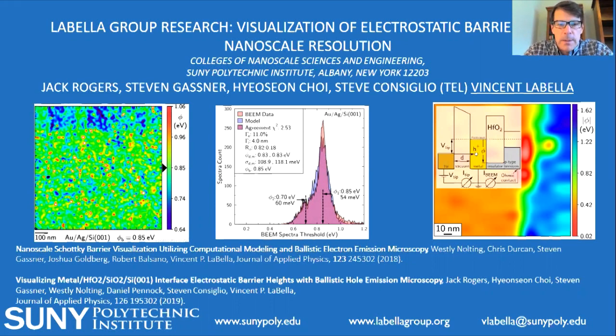This work is done in conjunction with a group of hardworking graduate students and undergraduate students, as well as some industrial collaborators, Steve Consiglio at TEL. And what you're looking at here is a map of the electrostatic barrier that forms between a metal and semiconductor. The energy here is the energy that a carrier needs to have to make it over the barrier. And this is resolved spatially over a square micron.